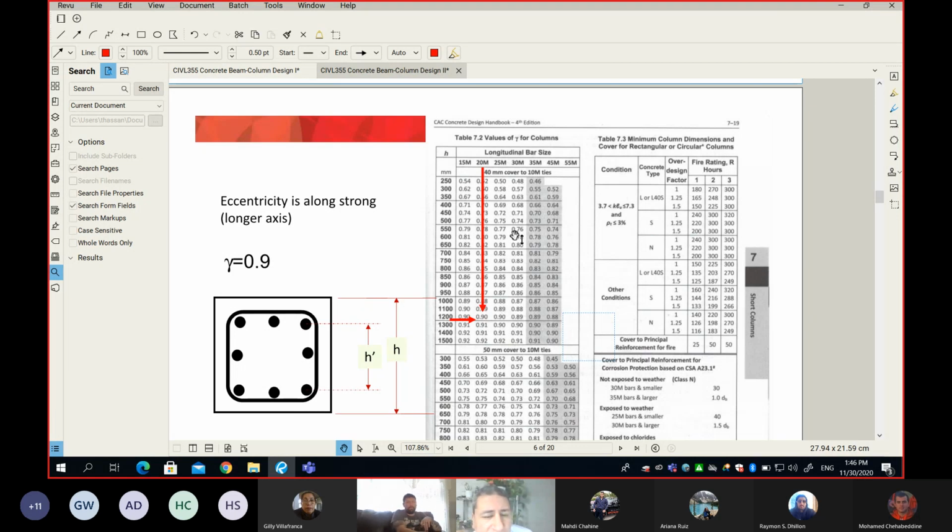However, the interaction diagram needs some parameters before you do that. And those parameters are simply which interaction diagram, because we've seen last class, we have so many of them, a total of 76 interaction diagrams. And we know why. Some of them are designed for different f'c.